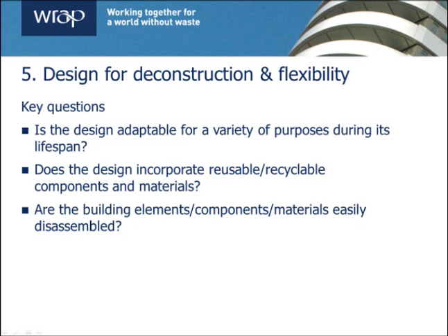There are a number of challenges associated with designing for deconstruction and flexibility, as it is difficult to ensure that the design information is retained throughout the life of the building. This is generally longer than the involvement of the original professionals, and information does not tend to be transferred when buildings change hands. To address this problem, materials can be marked with their original specifications, which will also help in any future repair and maintenance.